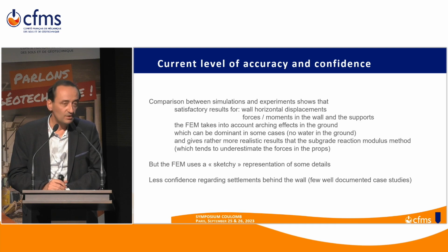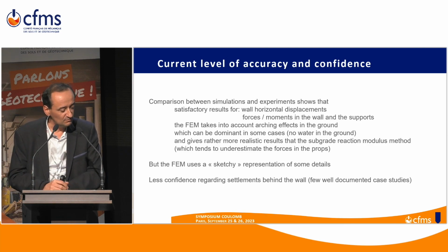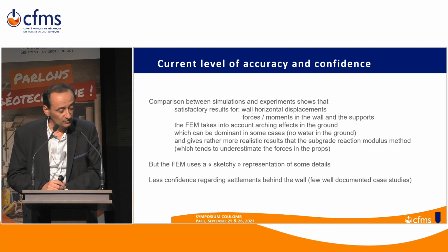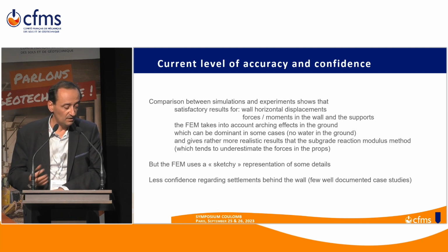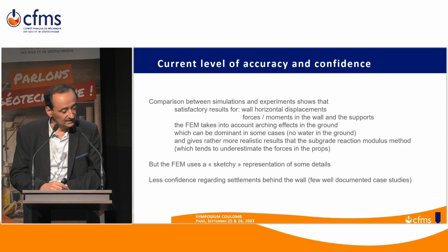Okay. Nevertheless, well, as I mentioned before, there are some details that are relatively grossly represented or purely ignored. And also, I would like to mention that we have less confidence regarding the settlements behind the walls because we actually lack documented case studies. It's difficult to get measurements because the site is used for many other things than just placing targets. So we lack appropriate data to be sure that the settlements are properly predicted by the models.